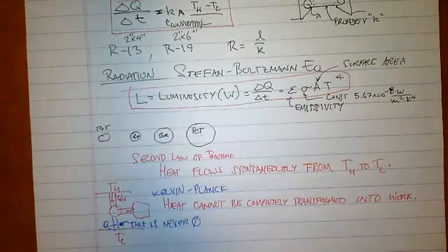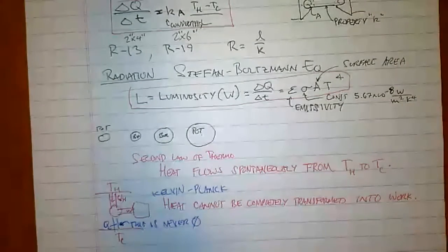There's another one about Carnot engines, and it says all reversible engines operating between the same two constant temperatures, TH and TL, have the same efficiency. Any irreversible engine operating between the same two fixed temperatures will have an efficiency less than this. So basically, the Carnot engine is the most efficient, is another way of saying it.